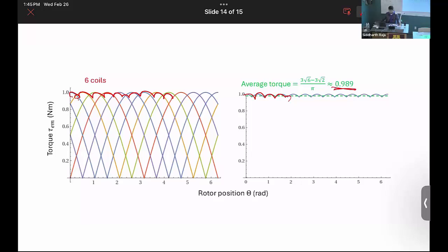Is the angle of the windings, is that also to decrease torque ripples, or is that for some reason on the rotor? Oh, the reason we have skewed it like this. That is so when we have, let's say this rotor is not skewed, right? So here we have air gap and here we have iron. As this rotor rotates, the magnetic field will prefer to go through the iron, but not through the air gap. So as the rotor rotates, the magnetic field keeps moving around back and forth, right? So that is going to create some kind of pulsation in your rotor torque. So you skew it so that when the magnetic field from here goes from this point to this point, the magnetic field on the bottom would come from this point to this point. So on average, you don't get that pulsation.